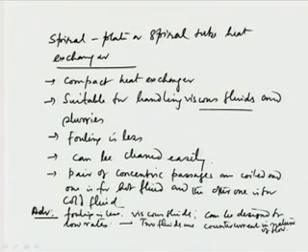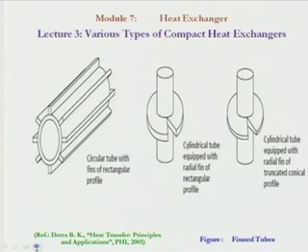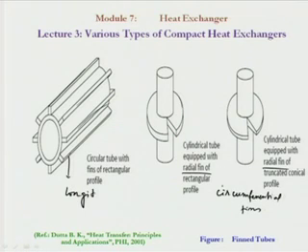Okay. So, now in addition to this spiral tube heat exchanger, there is another one which we have already discussed previously. The fin tube heat exchangers are also there. In this case, the tubes have some fins. You can see these lateral fins, and these are circumferential fins. You can see that it is radial, or circumferential, whatever you say. This is a rectangular profile, and these are circular tubes with transverse fins or longitudinal fins.